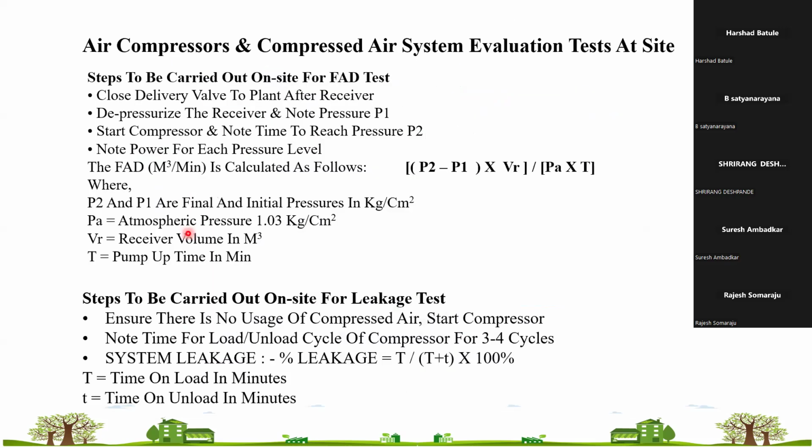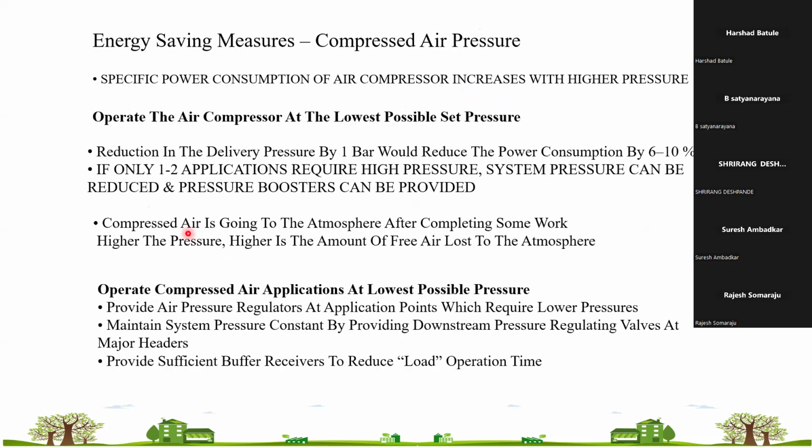So these are some different efficient operations, termed energy saving methodologies, but these are really just efficient operation of compressors. We can see that we should operate the air compressor at the lowest possible pressure. Whatever your user's highest pressure requirement is, we can do good engineering and set the compressor outlet pressure near to that higher pressure requirement. Then operate compressed air applications at the lowest possible pressure.